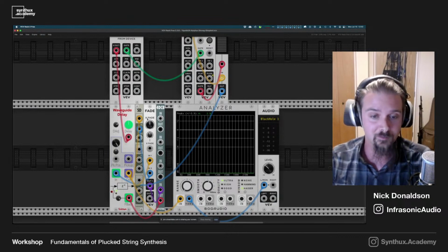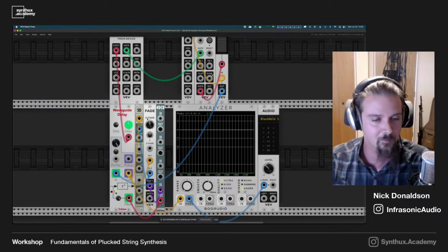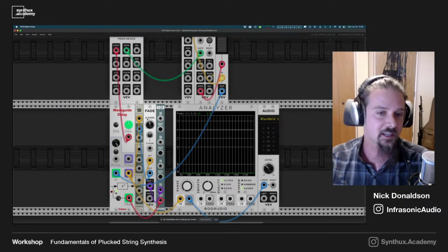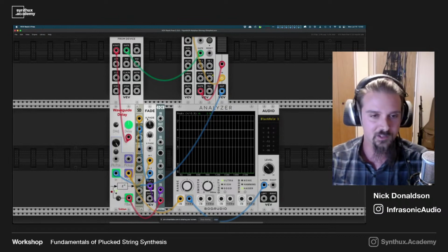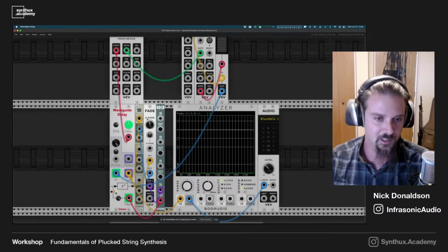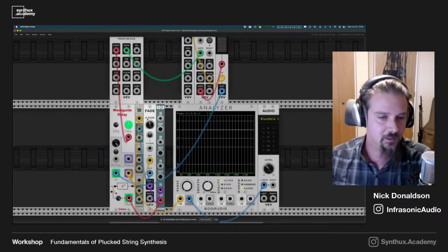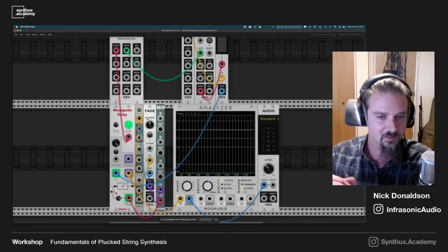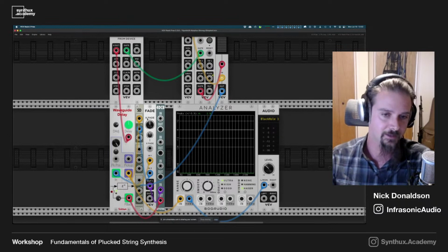In particular, infinite impulse response filters, which are most of the popular synthesizer digital filters and emulations thereof, actually have non-linear phase responses, and in particular around the cutoff, the delay is frequency dependent.